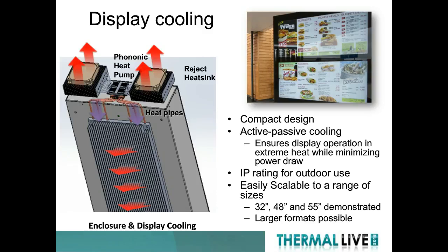And this is without burdening that system with something that requires 100% duty cycle or 100% active cooling, when that's simply not necessary for the primary portion of the operating life of these systems. However, everybody wants to get their slushy from the drive-through when it's 100 degrees outside. The display doesn't like that, and it needs to have the ability to dissipate that heat. And the options are to put large heat sinks on these and burden them with external volumes, or to integrate something like an active-passive cooling scheme to enable them to be compact form factors without affecting their ability to survive in extreme conditions in both heating and cooling.